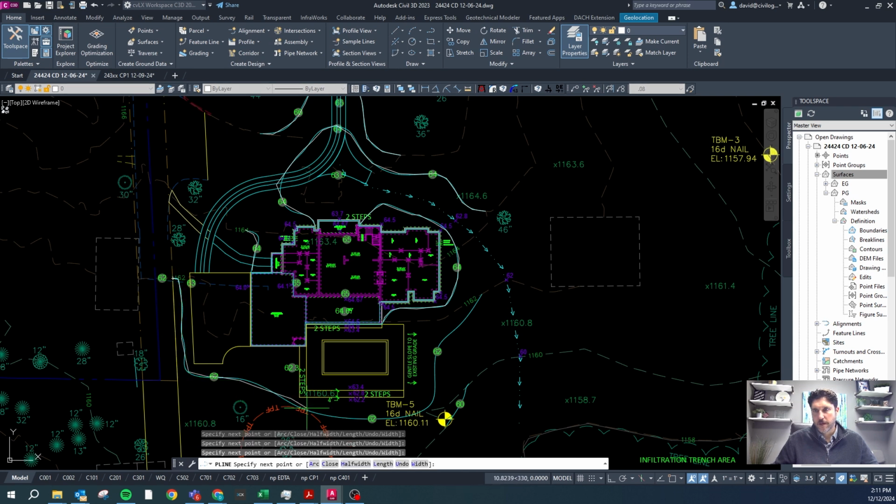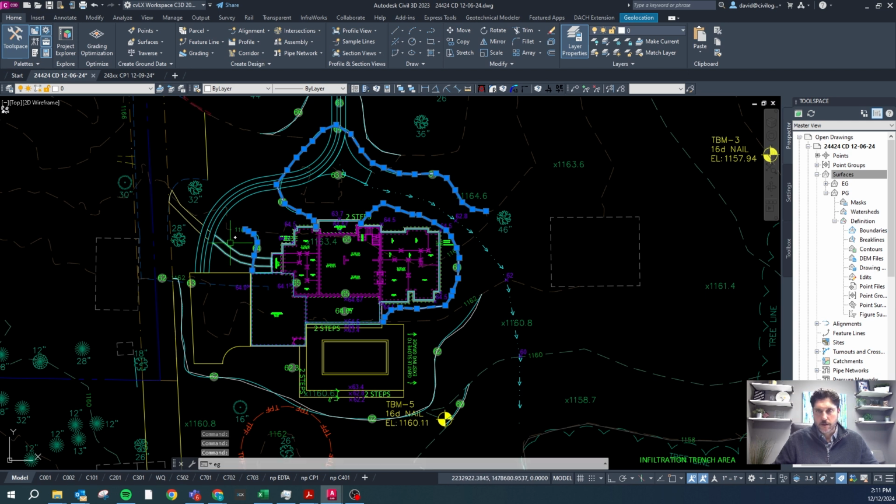And this is going to be fine for a conceptual or a preliminary takeoff. In addition to these lines, I can also use this command EG to match elevation. And now when I select this, that's on the proper elevation. EG, these three are 64, that one's 62, and that one's 66.